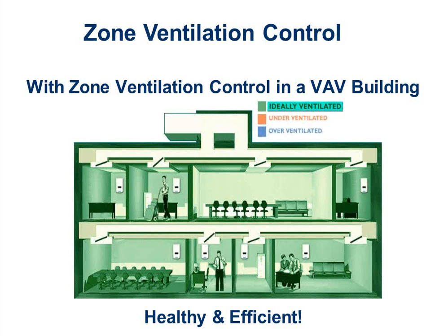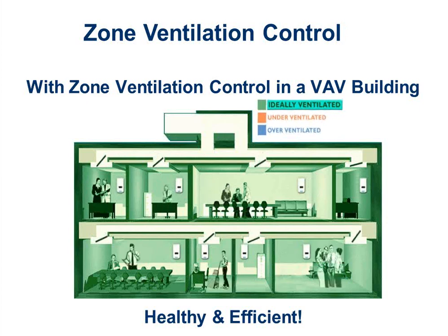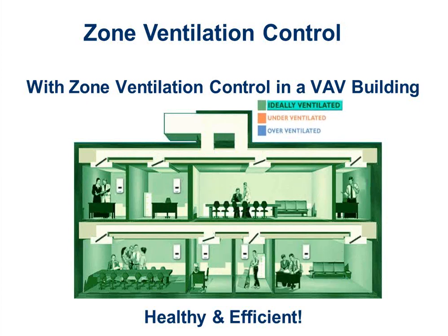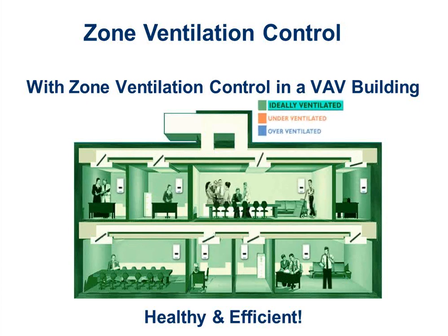The only place that I recommend using return air CO2 sensors is going to be like in a school gymnasium. That's because it's one big open room. It doesn't matter if the kids are in the East Gym or the West Gym, all that air volume is basically the same. And if I put it on the wall, someone's going to mess with it and knock it down anyway, so I might as well put it in the return duct.